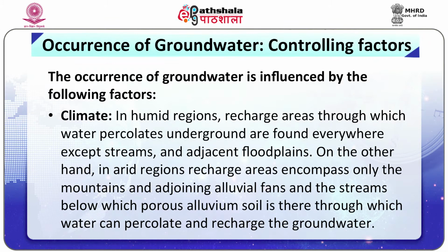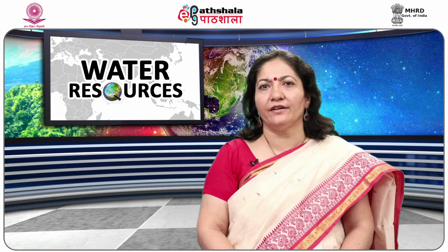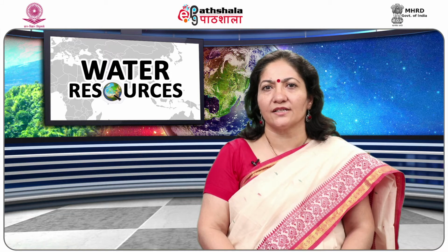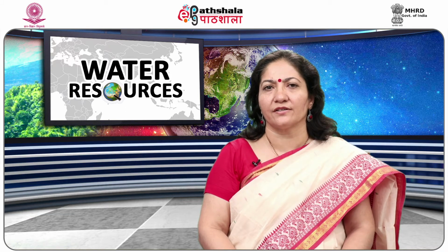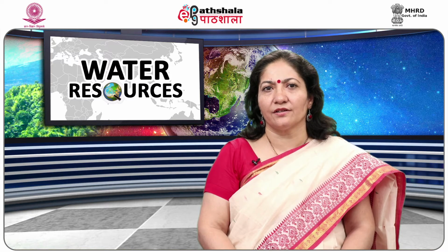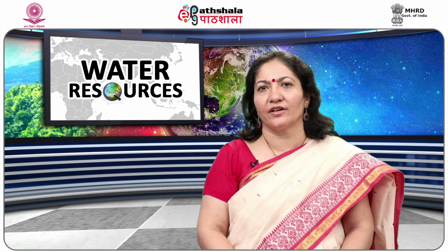In humid regions, recharge areas through which water percolates underground are found everywhere except streams and adjacent floodplains. On the other hand, in arid regions, recharge areas encompass only the mountains and adjoining alluvial fans and the streams, below which porous alluvium soil is there through which water can percolate and recharge the groundwater. Groundwater is available at great depth in dry or arid regions, whereas it exists at shallow depth in humid areas. Seasonally, the water table rises during the rainy season and sinks in the dry season.